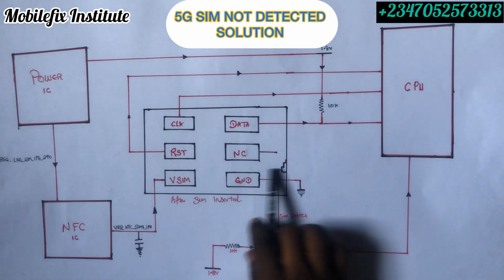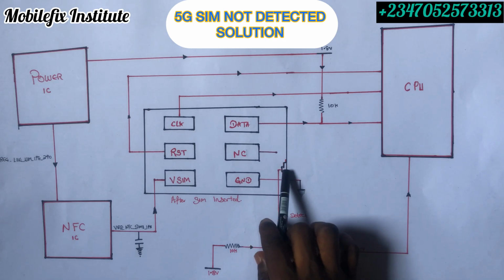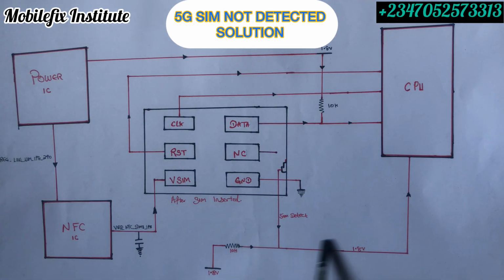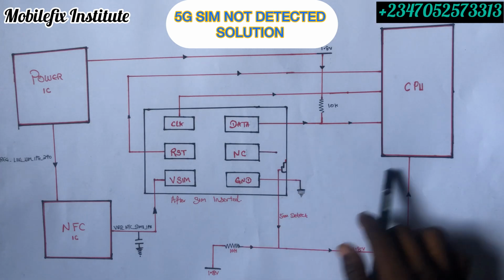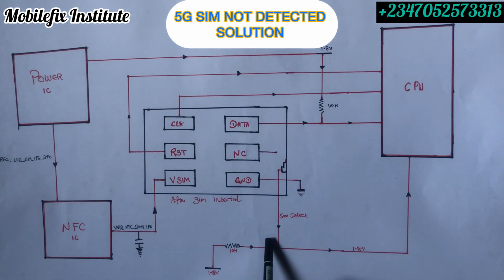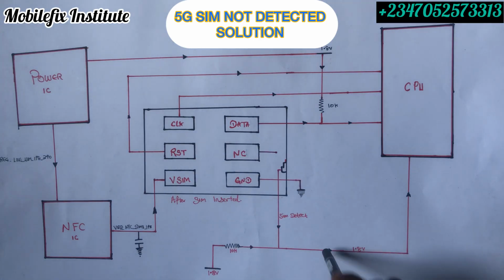You turn off your phone, insert your SIM card tray. With the SIM card tray, you disconnect this line from ground, then you test this side. You get value from your CPU side. But if you turn on the phone, the CPU will detect that the SIM card is connected, because you disconnect this line. Now this is how these lines work. So this is the first line you have to troubleshoot after taking your diode reading.